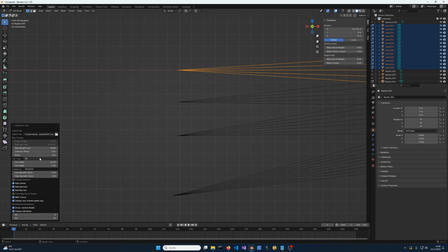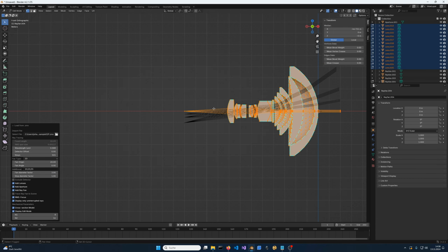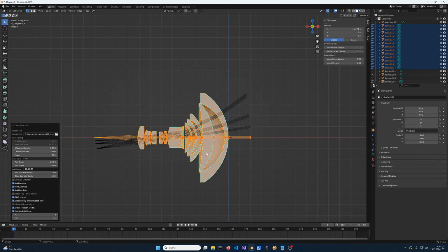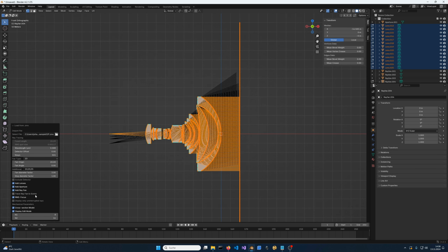Here so far, I've only shown a 2D ray fan. However, a 2D ray fan is not really accurate for calculating the RMS focus, particularly when you're looking at off-axis angles. Then you would need one of the 3D ray fan options. However, I'm not going to demonstrate this with this lens, because if we display the entire ray fan here, you can see that only a very small fraction of the initial ray fan actually passes through the lens and makes it to the image sensor, which again is one of these deficiencies with my current implementation, and needs to be solved by a better implementation in the future.